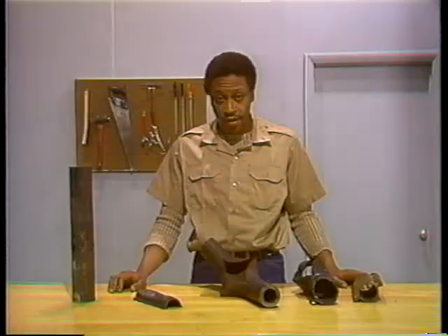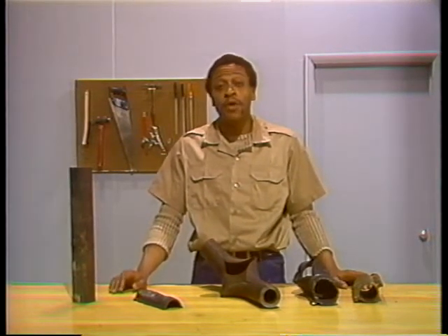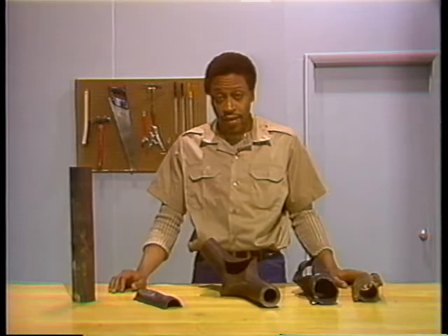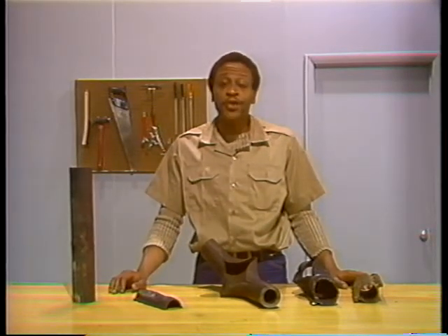Tube enlargement is common in superheater tubes. It appears as a uniform enlargement of a portion of the tube. The overheating that causes it is milder than the temperatures responsible for ruptures and cracking. But if an enlarged tube stays in service, it will eventually rupture or crack.